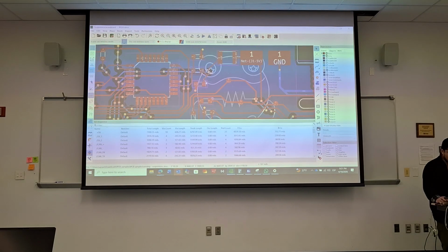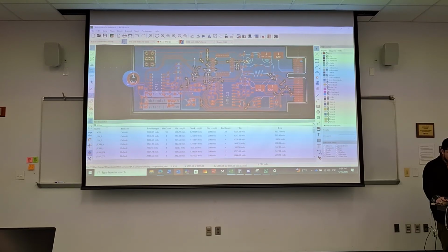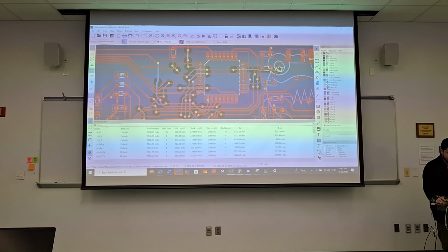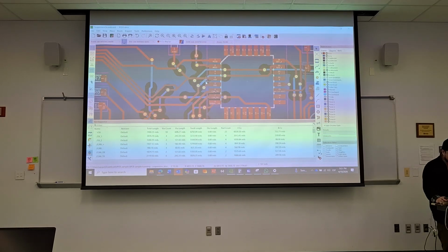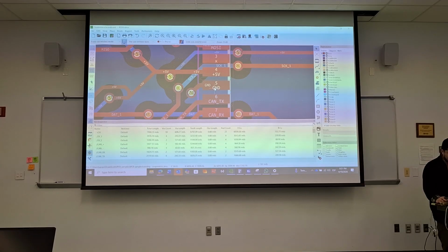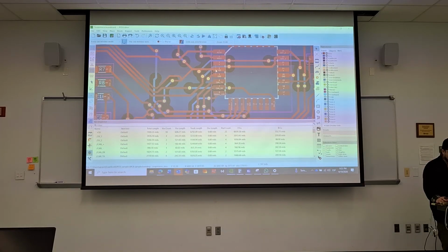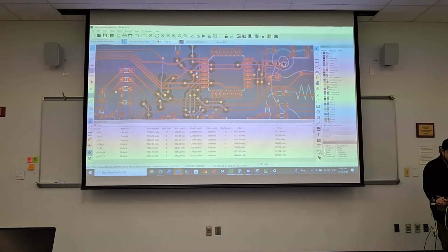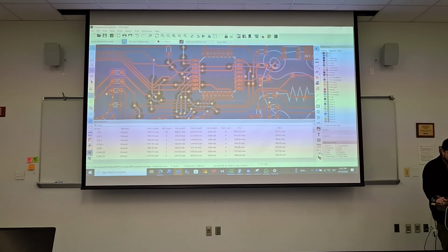It was one of these boards that I saw. Well, I don't see the bypass capacitors on this, and I'm pretty sure there's a microcontroller. Yeah, so for example, I would expect pin 4 and pin 5 to be VCC. So I would prioritize that bypass. I'm assuming one of these is the bypass capacitor somewhere.